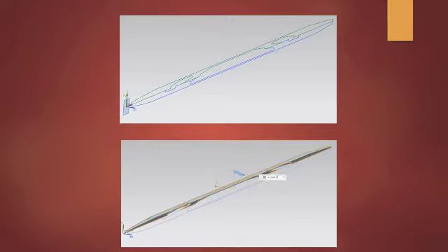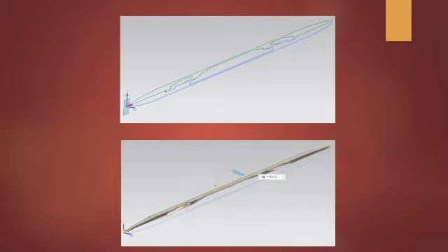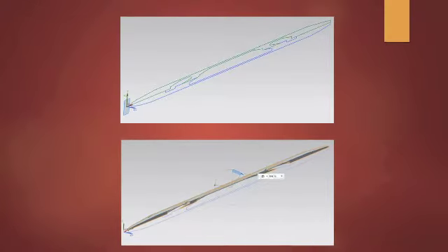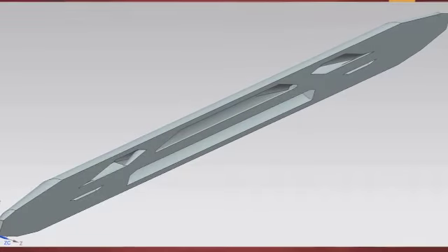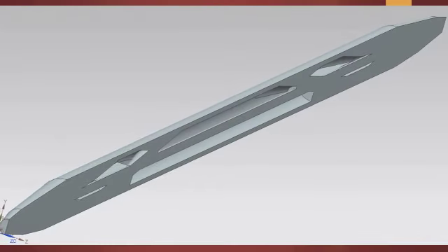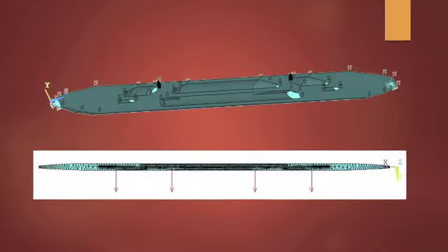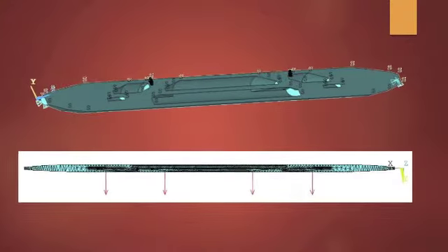Furthermore, rather than cutting the cross-section in half, we kept both the upper half and lower half of the cross-section. We revolved each half 90 degrees both ways so that they met at the center. Finally, in order to further reduce the sharp points and edges, we extruded a small diameter through the center of the beam. The same loads and boundary conditions were applied in ANSYS.